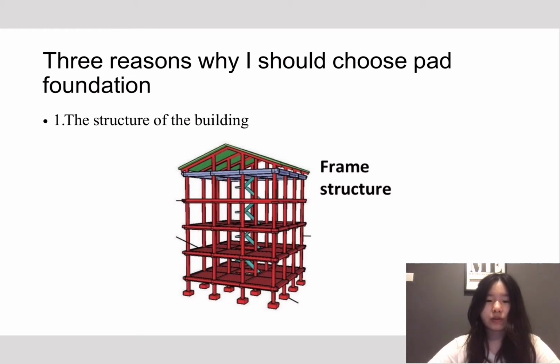Pad foundation is more economic than other foundations. Considering that there is a residential area and we do not want too much construction noise, it is very appropriate to choose pad foundation with less excavation and side pouring. Because it is only a three-story house without a basement, I think pad foundation is enough.